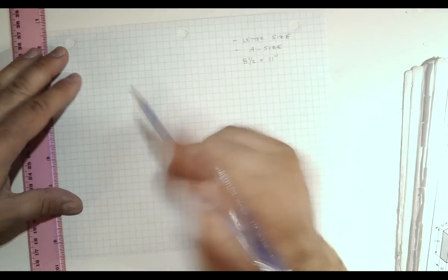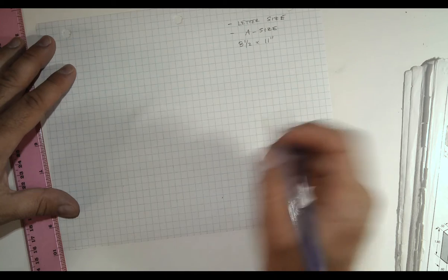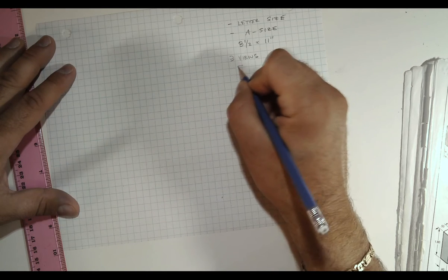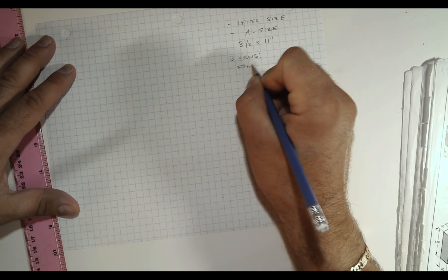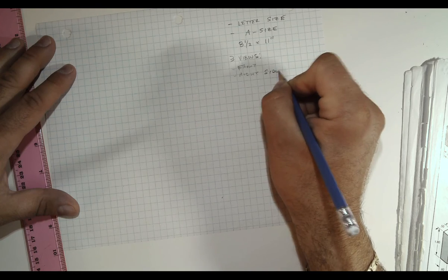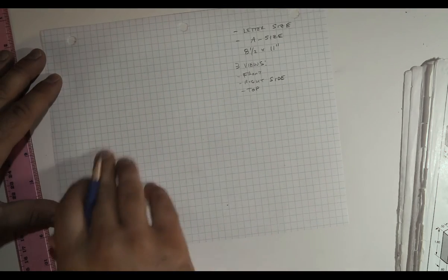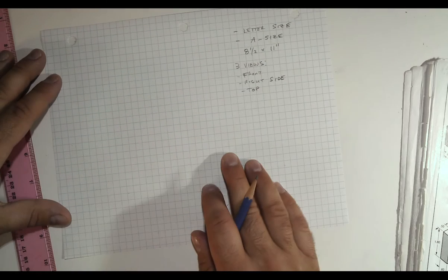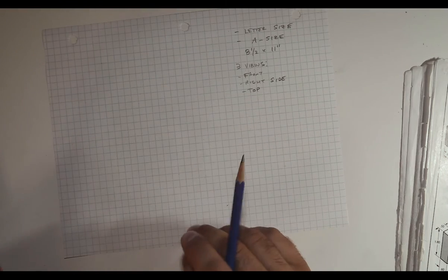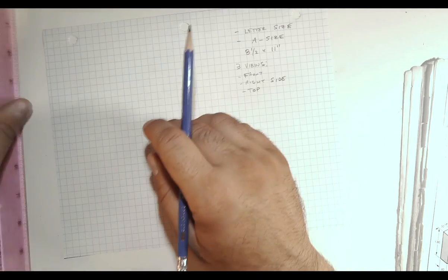So if I were to start imagining 3 views on this sheet, the book is asking you to draw 3 views. Front, right side, top. So we're going to arrange these views in this area of the paper. We don't want to draw the views really small and have a bunch of wasted paper space. We want to maximize this paper space.